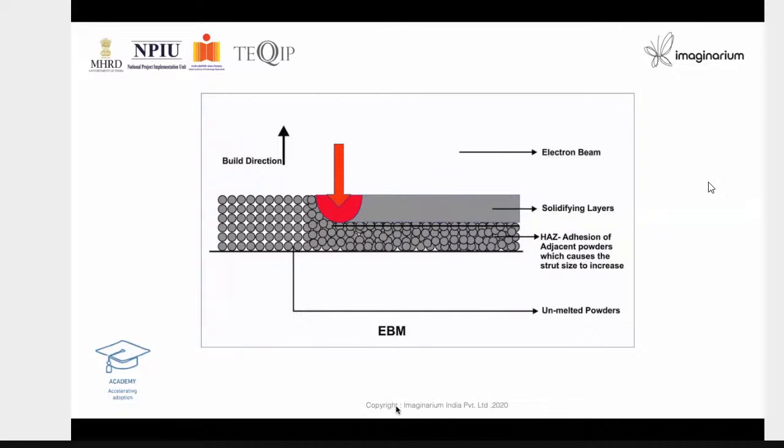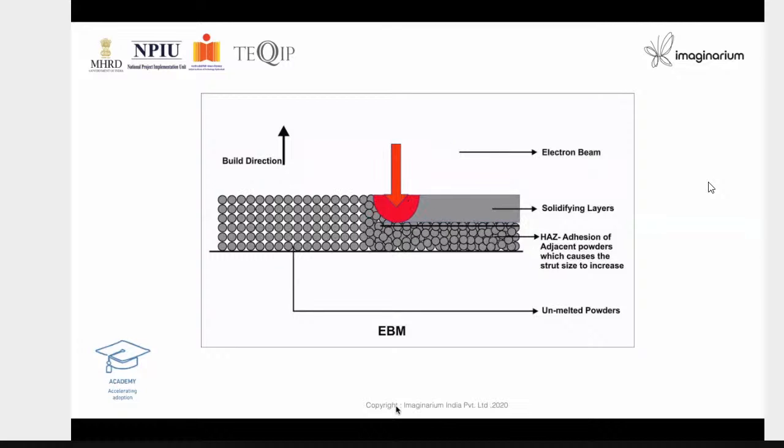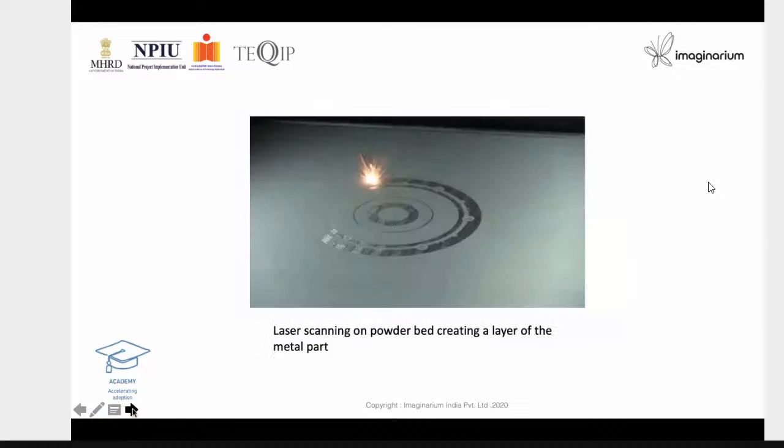So in order to anchor it, they'll have support, number one. Number two, they also have support to scavenge heat. It becomes very hot, and if we don't remove heat, warpage will happen. So metal, though it uses powder, invariably has a lot of supports, which are undesirable, but it is a necessary evil without which we cannot do it. But there are some technologies coming without support also.